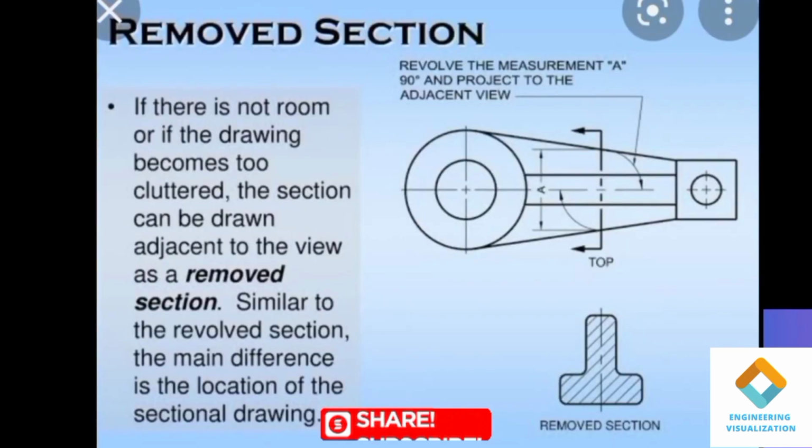It is similar to your revolved sectional view. The only difference is that here the view which has been revolved 90 degrees is placed at a certain distance. That's the difference between revolved and removed section. Removed and revolved sections are the same, only here the sectional view is shown separately at a certain distance. That's what we call a removed section.